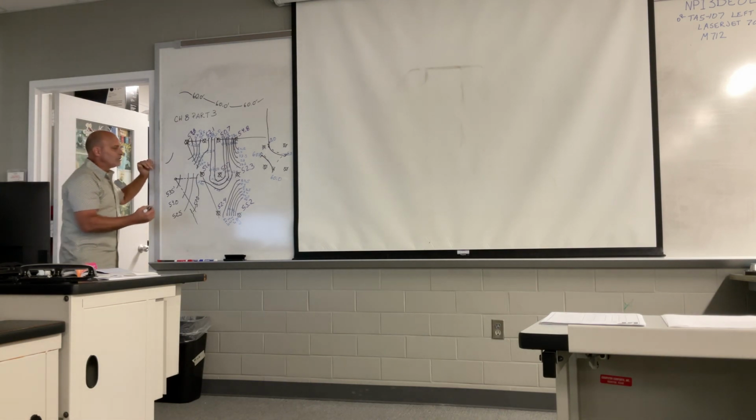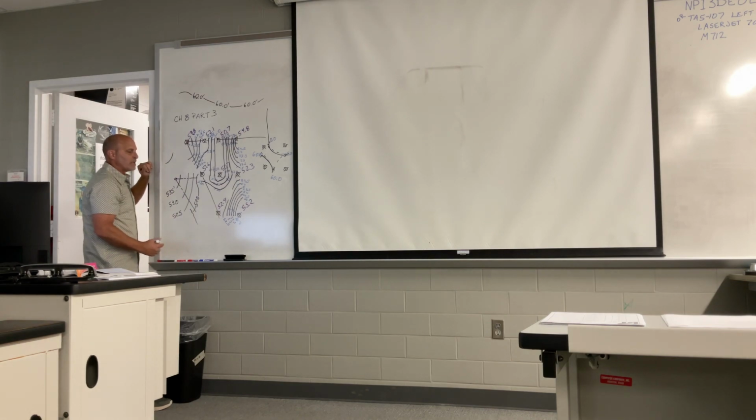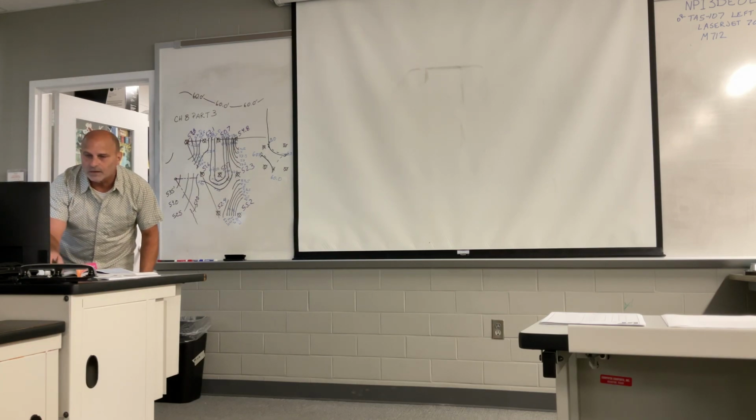If you go through and do something like the break command, BR and space bar, which will allow you to break a piece of that segment, use your spline, but use the spline that is called spline fit.